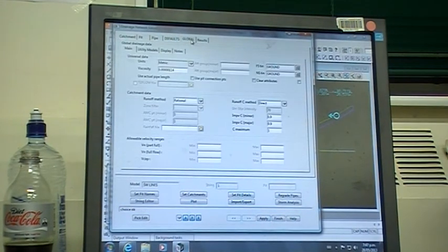So the first thing we're going to do is start setting these tabs, working from right to left. Global: anything that we set here as a default can be overwritten later if we want to change a piece of information for a specific manhole or a specific pipe. We can change that later. This is just a starting point for its design.